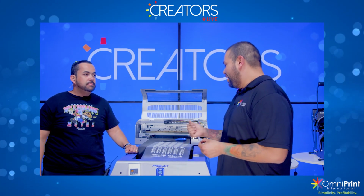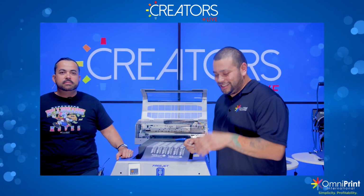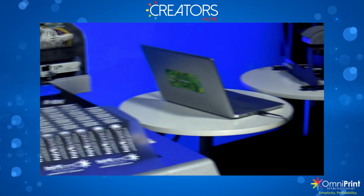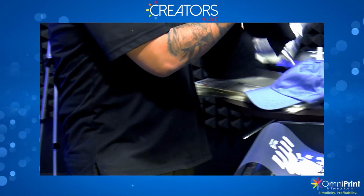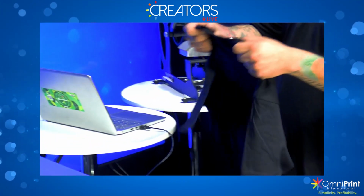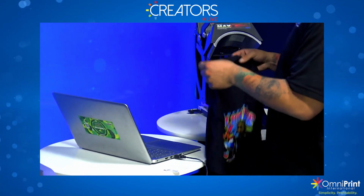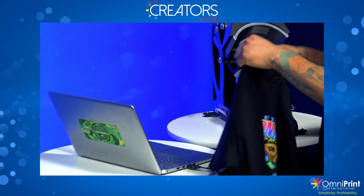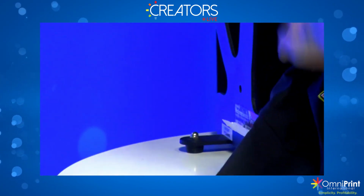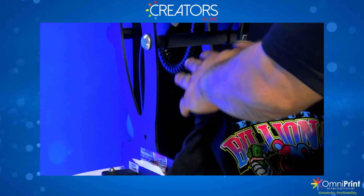And before, when I had a DTG, the tags, anybody who's tried that, it's a pain to be having to pre-treat the inside and do all that stuff. So for the tag, I do like to use the hat platen. The hat platen's a really nice small little heat press pad right here, so I don't have to be putting the whole shirt onto my press there. If you have those extra press attachments for your presses, they work great. In this case, I'm just going to use my hat platen here, which works great. So I'm just going to grab this, just wrap it around here. Check my pressure real quick, and I like to give it a little press, get rid of any moisture that's in there. Lift it back up, all right.